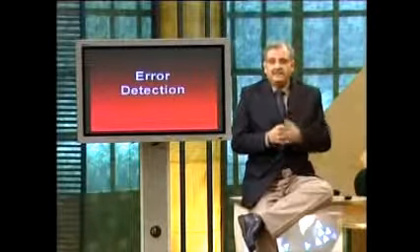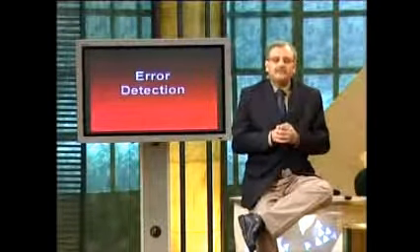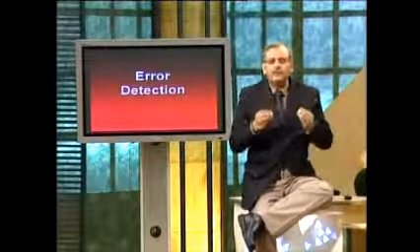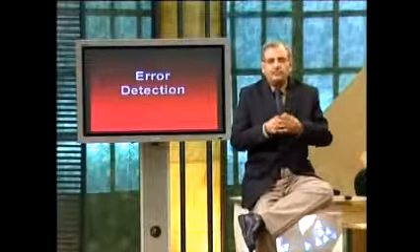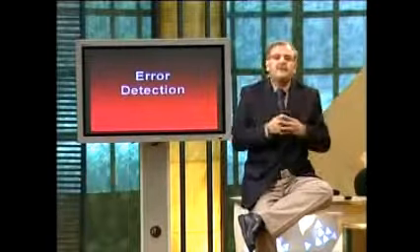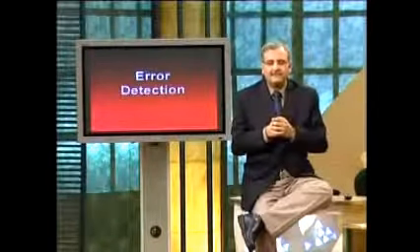In the first lecture, we mentioned that digital systems are very reliable systems. But even then, when you store information or when you transmit information, there are chances that the information is going to be corrupted. Now, what do you do? Well, in order to have secure information, you need to have a mechanism to detect errors if they have occurred, and perhaps try to remove those errors. Now, one simple method of detecting errors is using the parity bit.